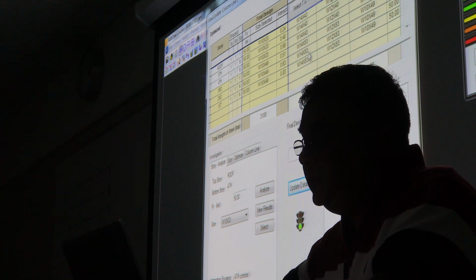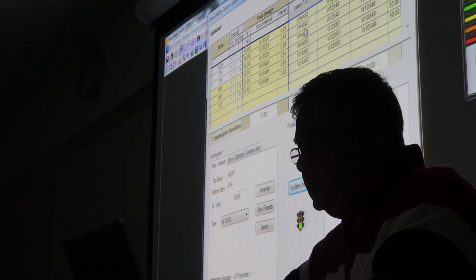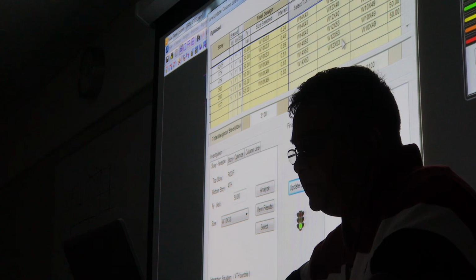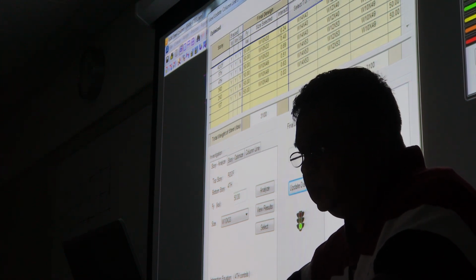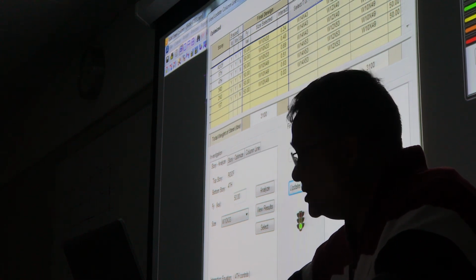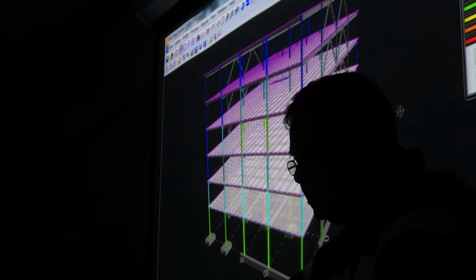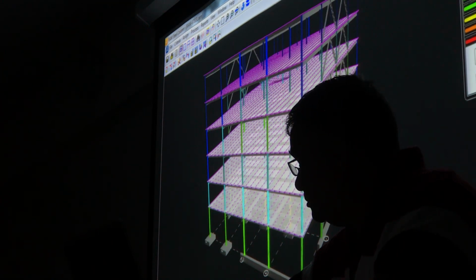If I want to use a W14 by size, this would be the size. Again, it's 14 by 53, whereas 10 by 49 was. If I'm using a W12 by, then 12 by 53, again, options. So these are my options. And the value of interaction is given as 0.69, and 0.69 should be somewhere here. This color, right?